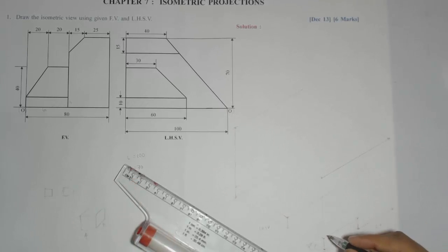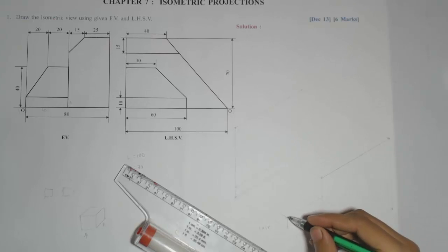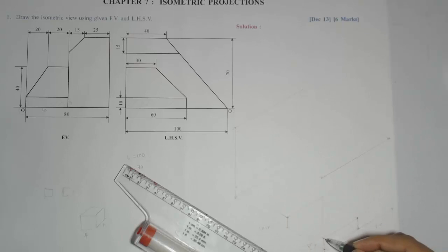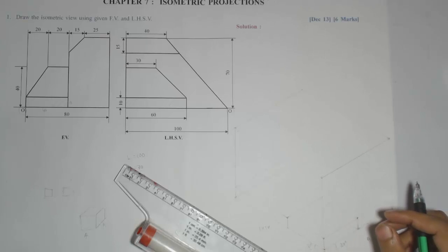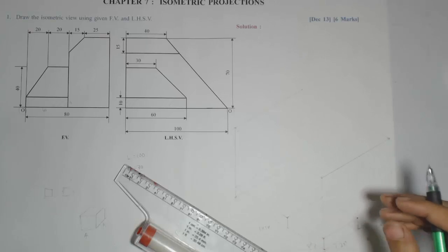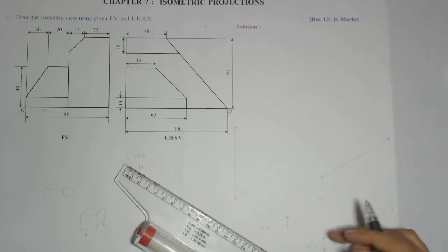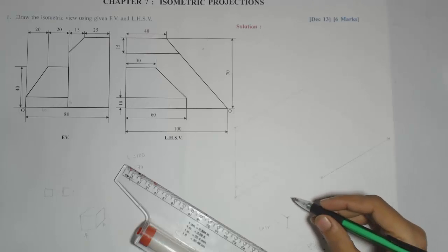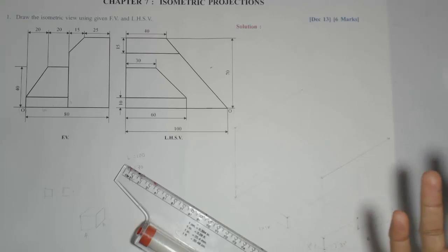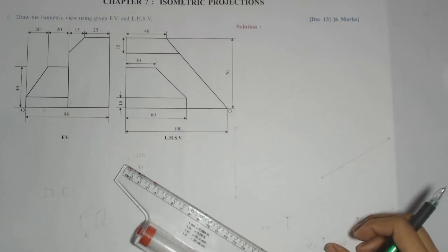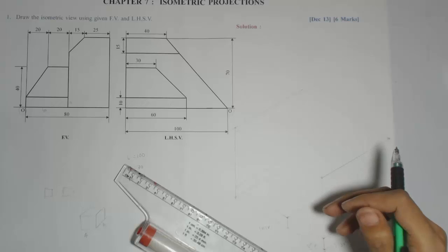Now after doing this, at 10 mm height, whatever the projectors, meaning corners, from these corners, they will be intersecting each other. So I will mark those points first, because that intersection will give me the top view. Because the base, which is starting from the bottom, if I join those four corners, that will become the base and will not be visible to the observer. Only the top, those intersections, will be visible.